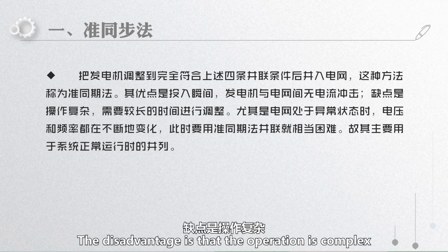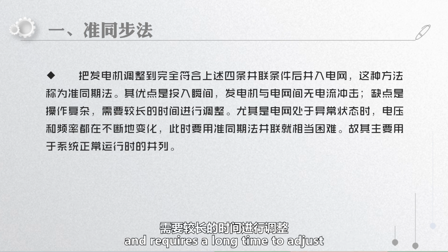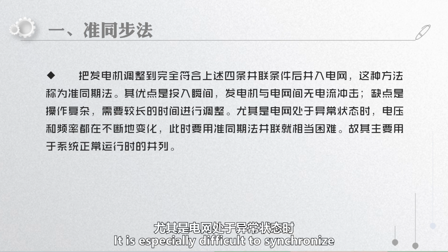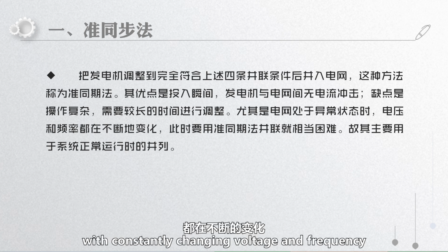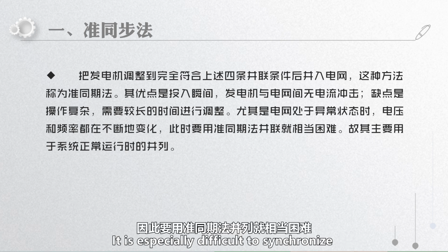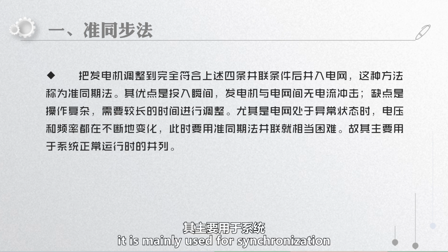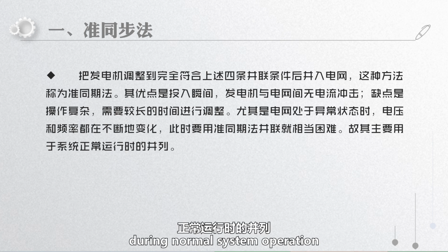The disadvantage is that the operation is complex and requires a long time to adjust. It's especially difficult to synchronize using the quasi-synchronous method when the grid is in an abnormal state with constantly changing voltage and frequency. Therefore, it's mainly used for synchronization during normal system operation.